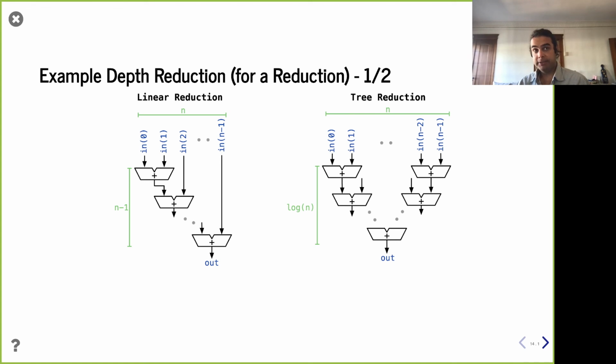If the output of my addition is saved to be the same size as the inputs, in this case, let's say 8-bit inputs, 8-bit output, it's possible that there's this overflow behavior, right, where I have 2 numbers added and the result appears to be smaller than the inputs because it's wrapped around. That's semantics, right? And so if I give my tools a design in which I have these numbers doing this addition, which because of the size of the inputs and the outputs, overflow is possible, let's say the input and output sizes are the same. If I accumulate these things in a linear order versus in a logarithmic order, that actually changes the numeric result at the end, potentially, depending on how the overflow works out, right?